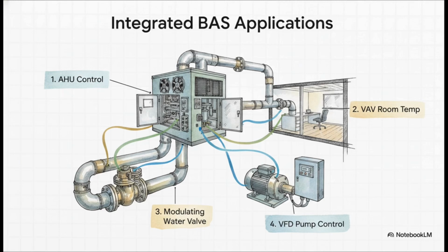You'll see them modulating chilled and hot water valves to maintain precise supply air temperatures, and they are constantly, and I mean constantly, commanding variable frequency drives, or VFDs, to ramp fans and pumps up and down efficiently. It truly is the universal language of HVAC mechanical control.